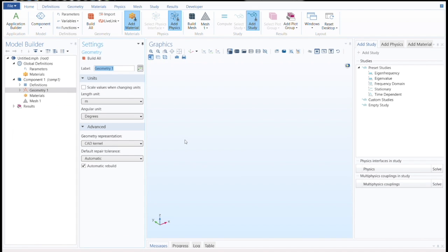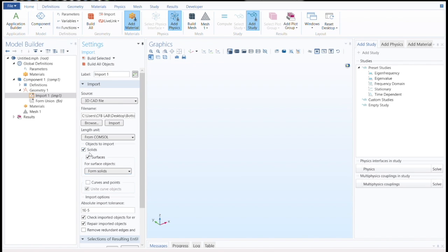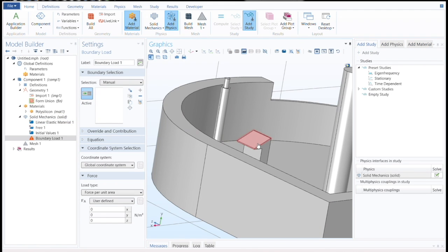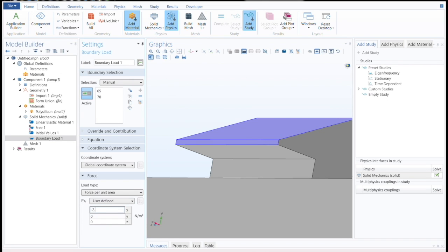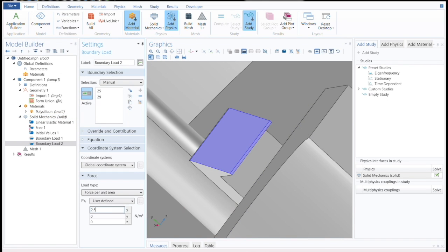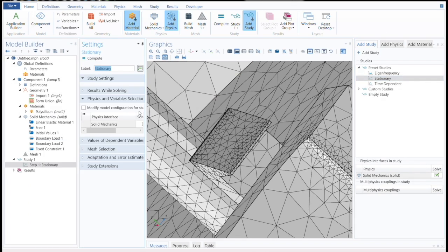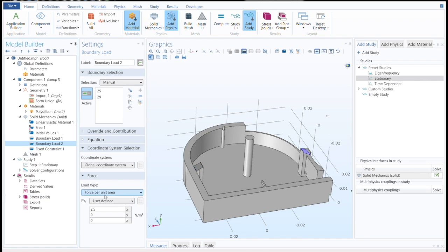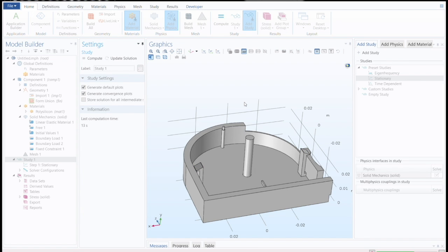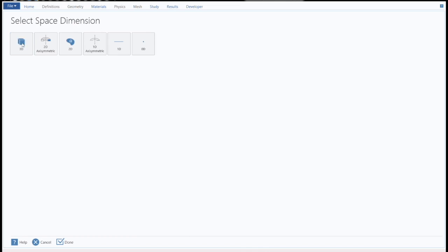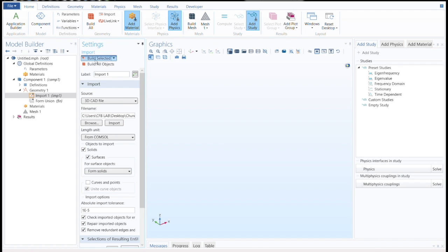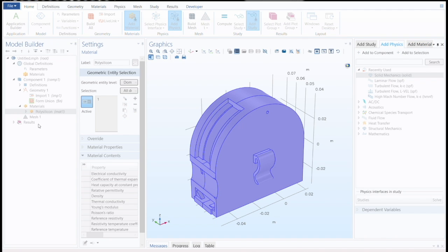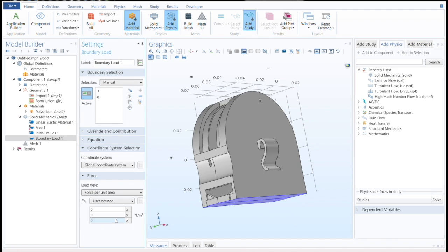To make sure our design sustains in reality, we used a mechanical analysis software called COMSOL for our newly designed product. For the clip fits, we imposed point and surface loads of 2.5 newtons and 10^6 repetitive cycles. As a result, there is no deformation in the clips even if pushed 10^6 times. To check the quality of our newly designed product, we imposed 2.5 newtons force on all surfaces like X, Y, Z directions on the body.